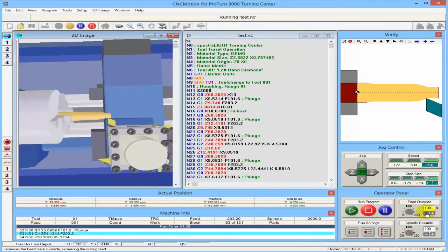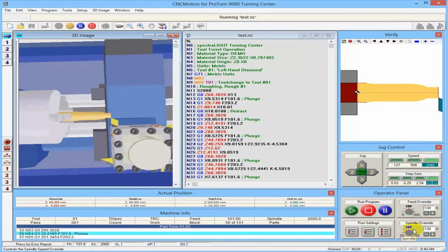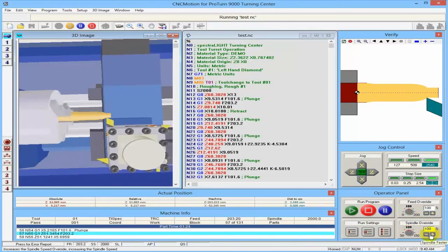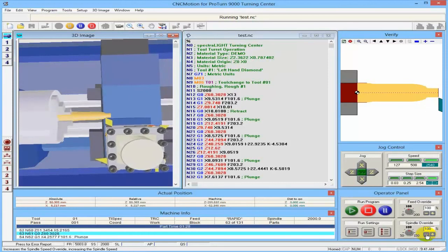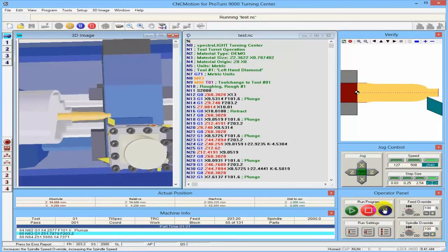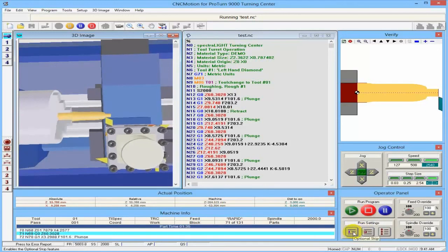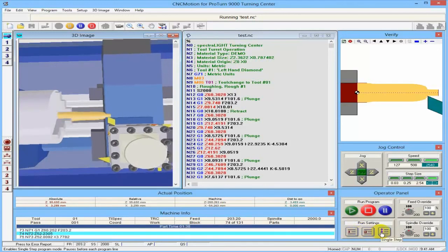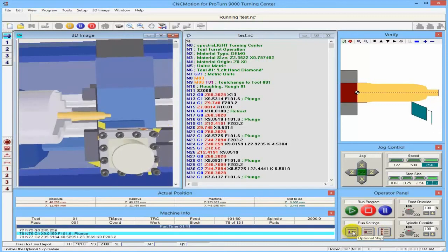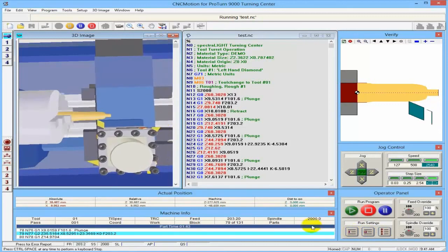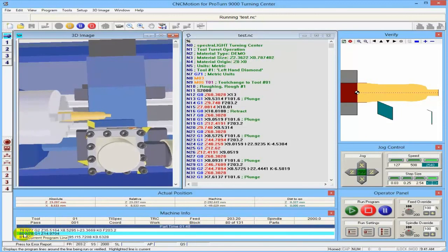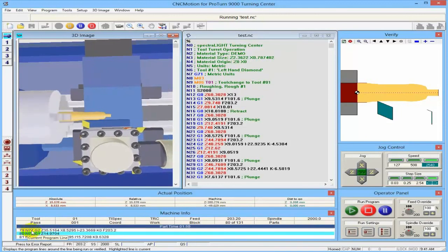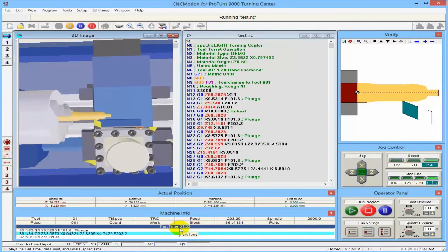And I can also increase the spindle speed override, increase the spindle rotation speed up and down. I can pause the program, play or stop the program. I can run it single line, single step, optional stop or optional skip, just like an industrial machine. All the G code lines are seen over here, and as you see, you can see the part time.